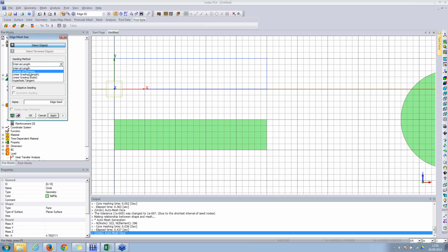This also allows us to have a more efficient mesh, because you may not want the same mesh size everywhere. If you are doing a very detailed analysis, you may want a finer mesh near the supports, or near where the loads are applied, but a coarser size of plate element elsewhere, at the boundaries for example.